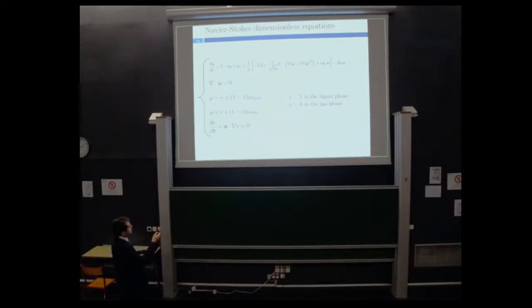So here, the pressure forces, the viscous forces here, assuming we're working with a Newtonian fluid. Here, we've got the capillary forces, so the forces at the interface, which involve the capillarity. And last, we've got here the gravity forces with our Bond number. The second equation corresponds to the continuity equation, assuming we are working with an incompressible fluid.